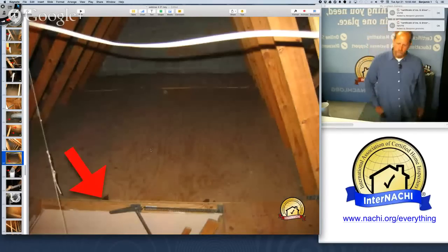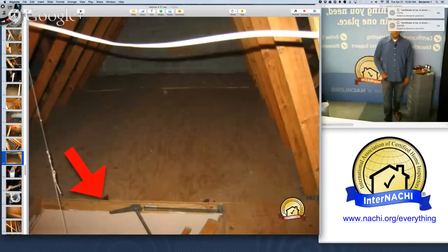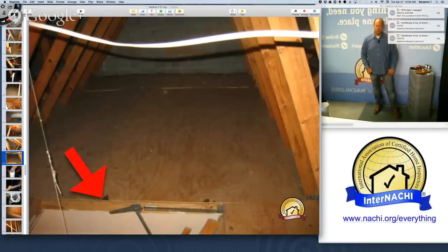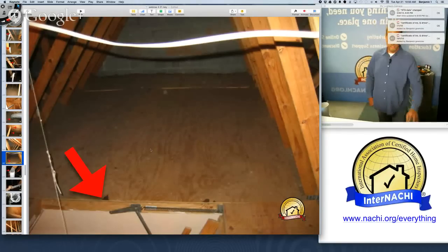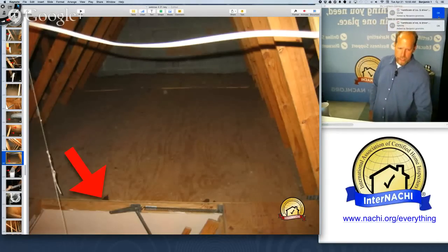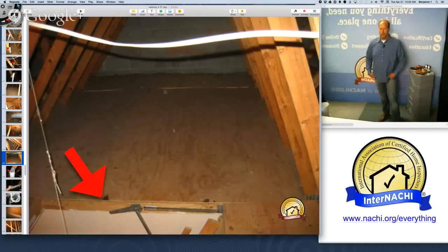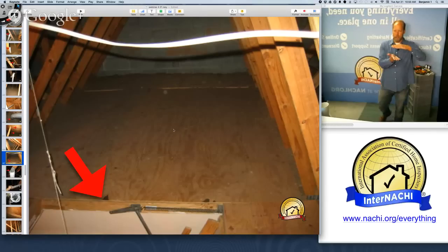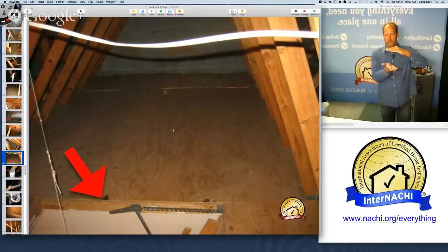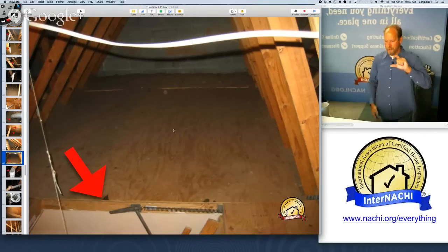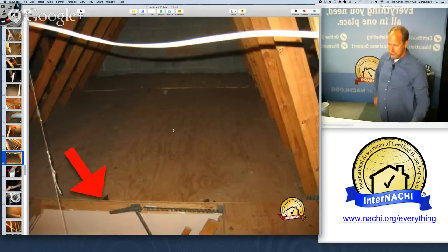except for this floor. So the bottom chord of this truss structure is only about 3.5 inches. And that means that there is a lack of insulation underneath this flooring, this plywood flooring that was applied in the attic space for extra storage. And so they compressed the insulation down to the height of the bottom chord of the roof truss structure. And it's only 3.5 inches thick. Ideally, we want 10, 12, 16 inches of insulation in this northern climate, cold climate.